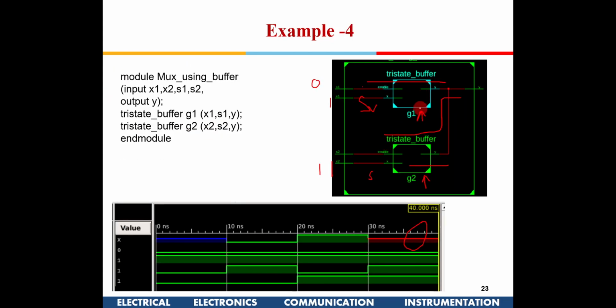It all depends on how you design it. If you do a detailed design at the gate level, more often than not you will be able to detect such faults. If you do behavioral level modeling, then many faults may go undetected. So that is the reason we should not just do a behavioral model and assume that our circuit will function without fault.